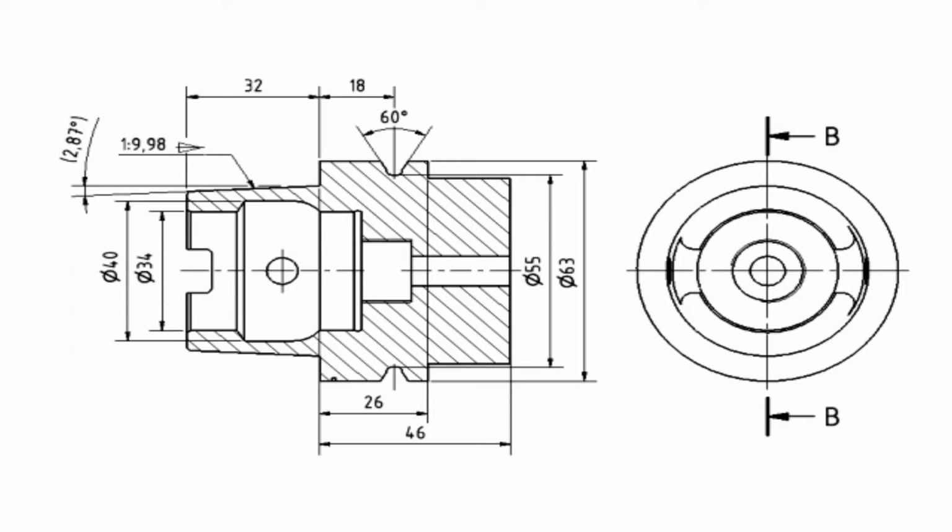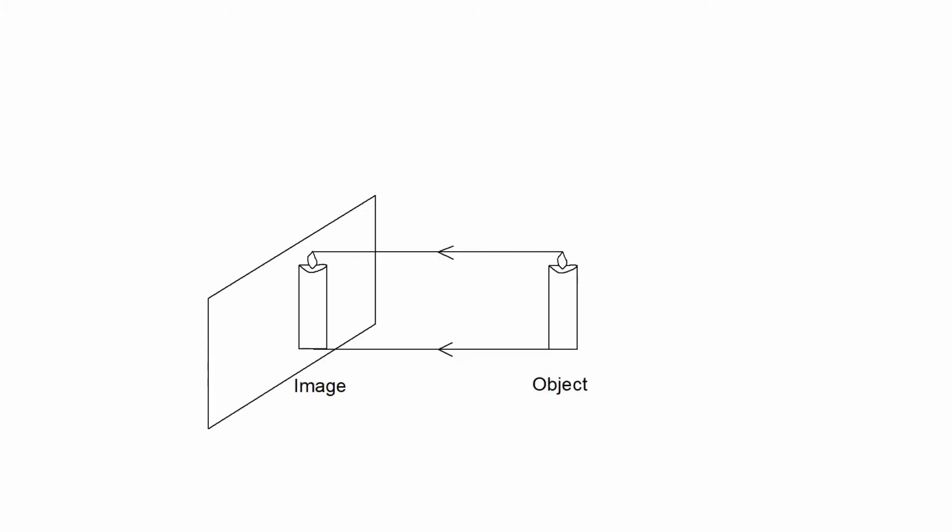For obtaining these images, we need planes, just like films or sensors in a camera. These planes on which images of an object are obtained are called planes of projection or picture plane. Usually two views are required to describe an object in engineering drawing and hence two planes are used. These two planes, as you can see, are mutually perpendicular. These two planes are called principal planes.